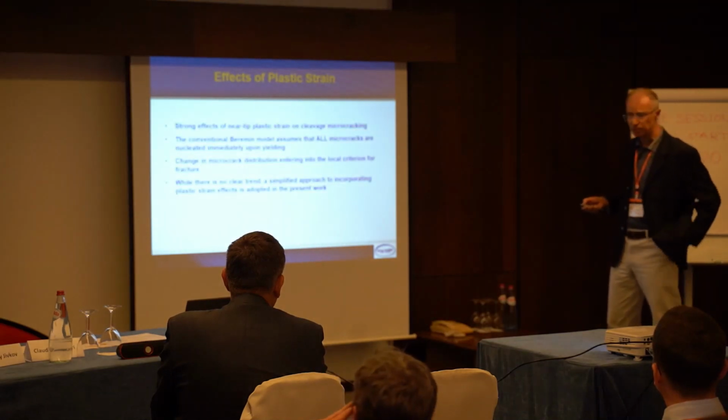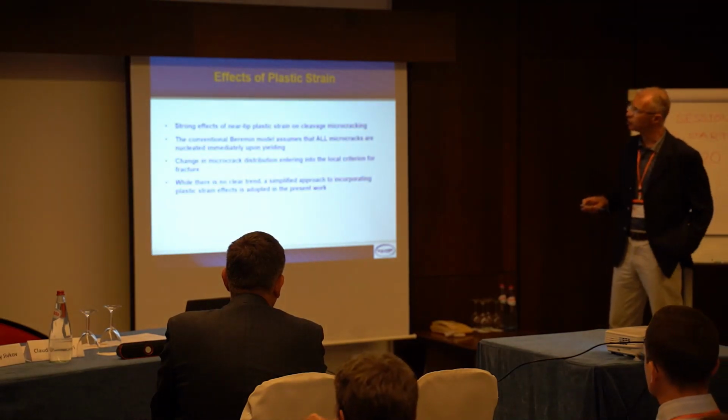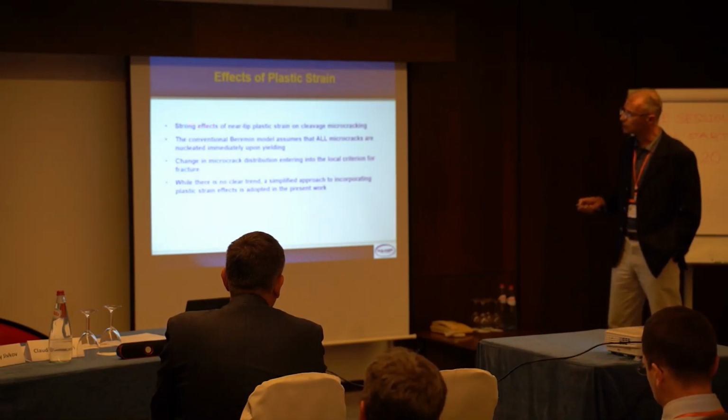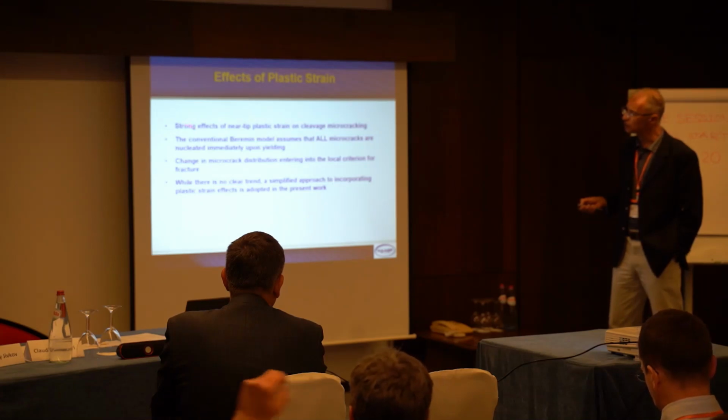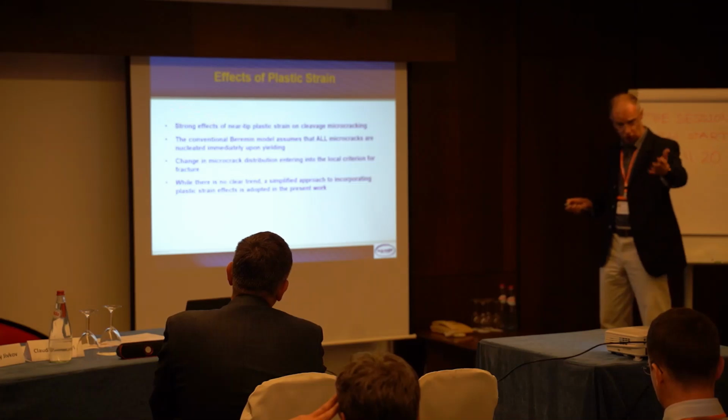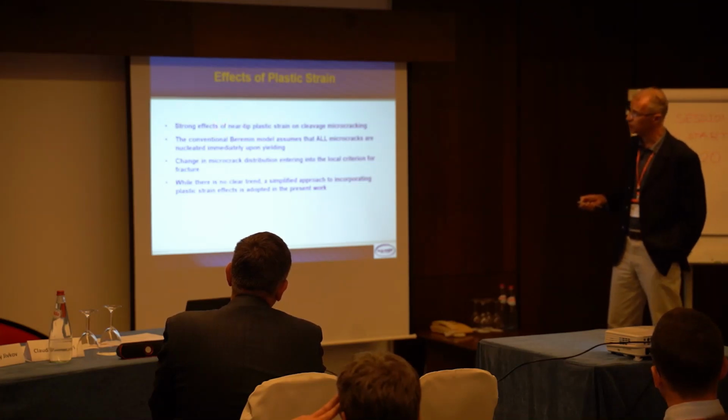So the Beremin model has been adopted for many years with relative success. But as we saw in a previous presentation, there are strong effects of plastic strain on cleavage microcracks.